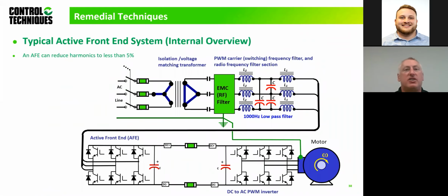Okay, so basically it's just going over what I explained, but with a schematic diagram, so you've got a clearer view of what's going on. The transformer is not part of the package, it's just showing the isolation transformer. But again, because it's a PWM output, we put an EMC filter on there if needed. It is optional. It's not that everything's going to go crazy without it. It's just to meet the EN norm of Europe that the EMC filter has been put in there.